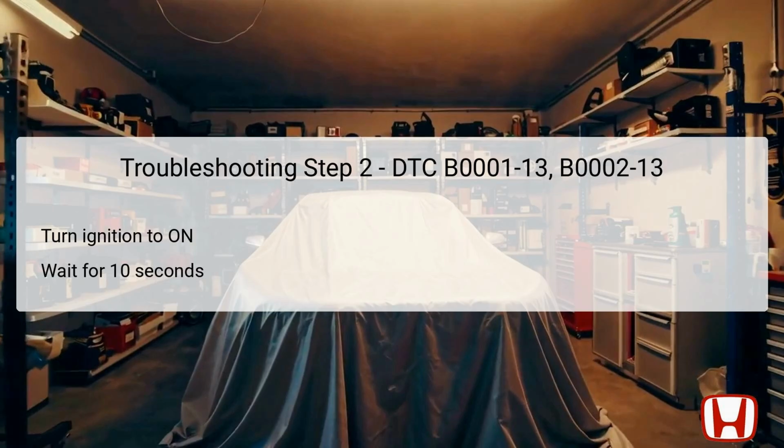It is crucial to wait for approximately 10 seconds following this to allow the airbag control unit time to complete its initial diagnostic check. Skipping this waiting period could lead to inaccurate diagnostics or missed DTCs that the airbag system may detect shortly after ignition is activated. Thus, this step is integral to ensuring that any present codes are identified before advancing further in the troubleshooting.